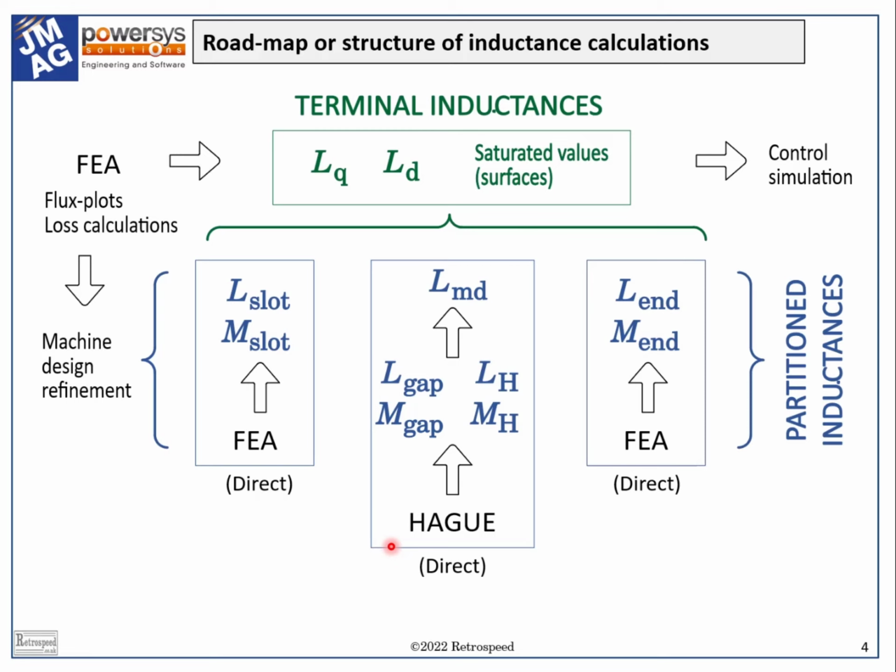The first is the theory of windings, that is, the disposition of coils and interconnectors, the layout of the winding. This is inseparable from the calculation of the air gap components of inductance, including the fundamental space harmonic and all the higher order and sometimes lower order space harmonics.